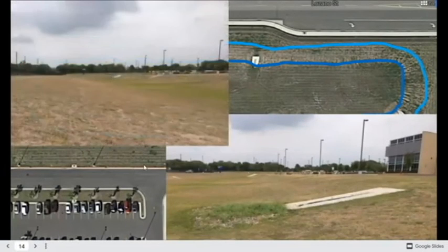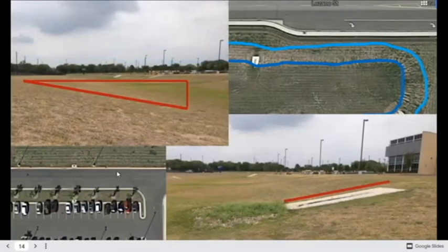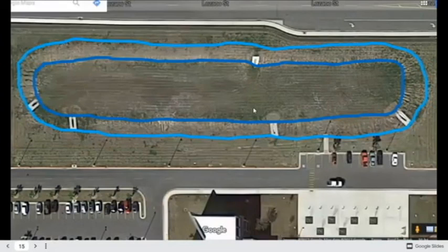And just as an example of how simple it is, one of the things that engineers do is calculate the rise over run of the slope, so that those who are going to build it, they usually tell them like, oh, this slope here, this is like 1 to 6, meaning it's a foot drop for 6 feet forward, rise over run, so that the contractors can put it in place. They don't give them an angle or anything like that. They give it to them in rise over run form.